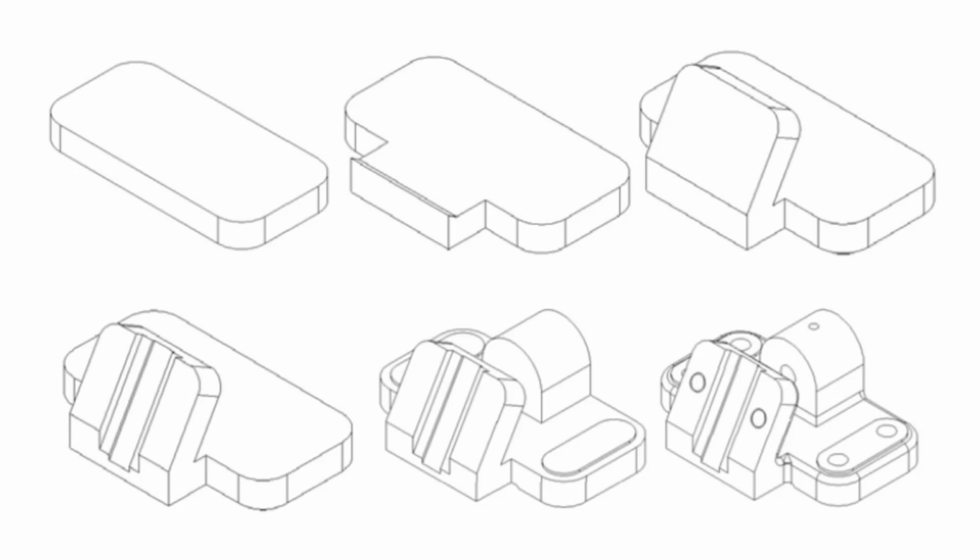The following steps may be used in modeling the vertical bearing support. We have the base as the first feature. We have the boss for the slot body, and then the slot body on top of it to be added at an inclination, a slot cut through, and a slot coming at the bottom of the base boss, and then you have other bosses for the holes. Finally, drilling all the holes, counterbore holes, simple holes and threaded holes onto the part and adding fillets at the sharp edges.